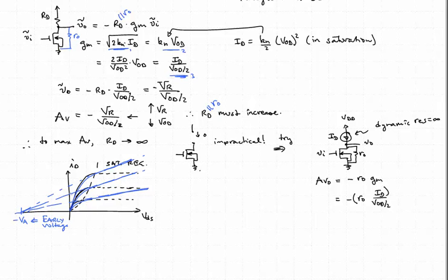And what we see is that it turns out that the dynamic resistance, so this right here, 1 over RO, has a slope with units of current over volts, so it's conductance, and it's equal to 1 over RO. You see that RO is actually a function of the operating current. RO turns out to be VA over ID, or RO times ID is equal to VA.